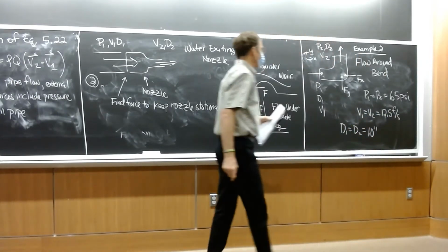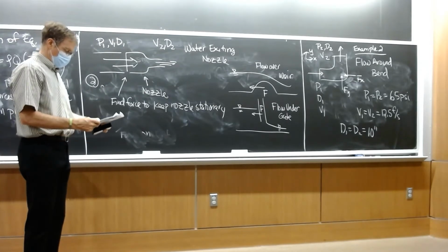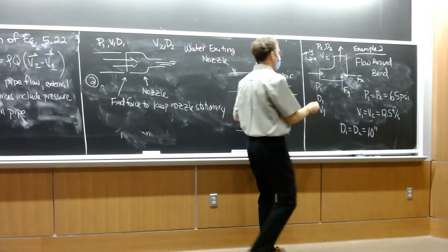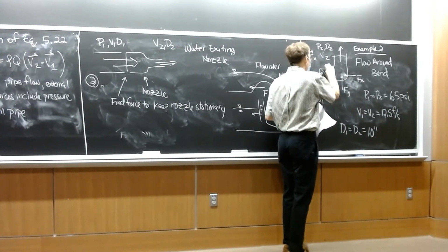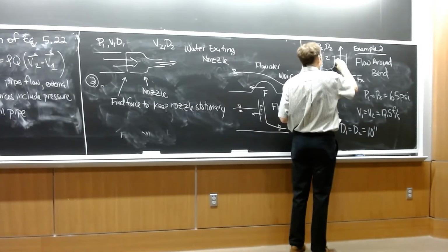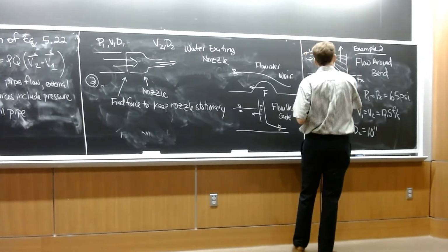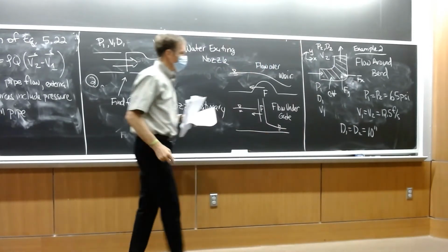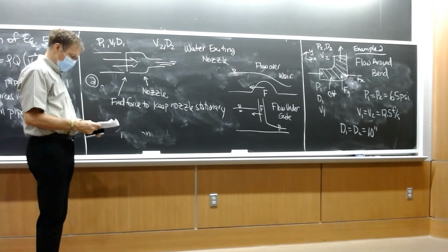This is a big water supply pipe. And so we think of there is this elbow, but what our control volume is actually the water inside that bend. So this is our control volume, and that elbow is actually putting a force on the water, and that's what we're analyzing.